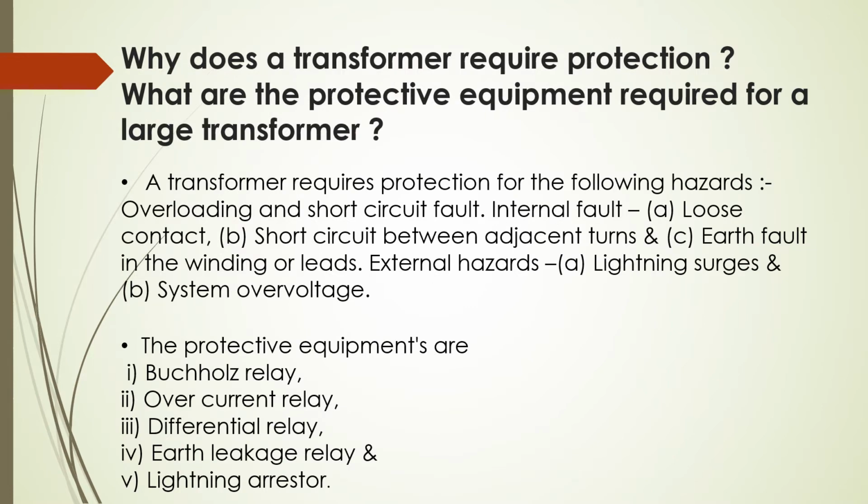Why does a transformer require protection? What are the protective equipment required for a large transformer? A transformer requires protection for the following hazards: overloading and short circuit fault, internal fault, loose contact, short circuit between the adjacent turns, earth fault in the winding or leads, external hazards like lightning surges,